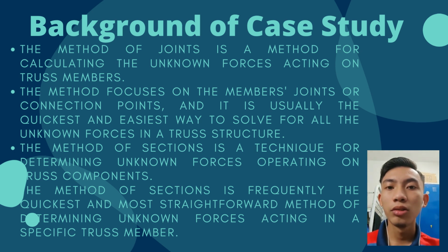Make a list of the equilibrium equations for each joint. The joint should be treated as a particle with force equations but not moment equations. We should be able to generate a high number of equations as a result. For each joint, the sum of forces in the x direction will be 0 and the sum of forces in the y direction will be 0.